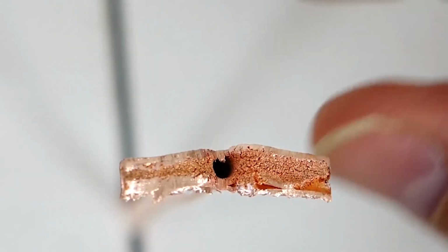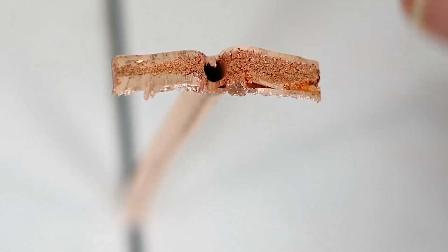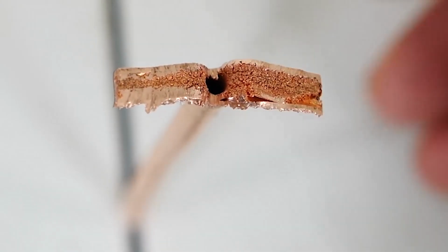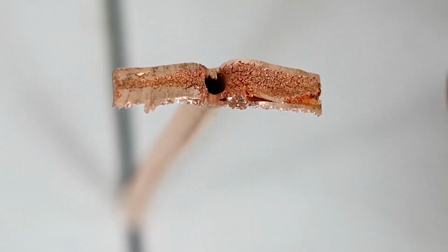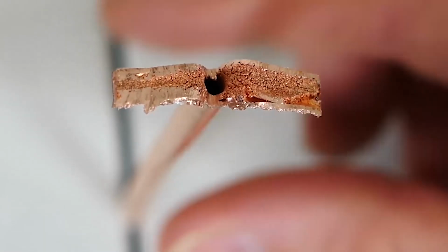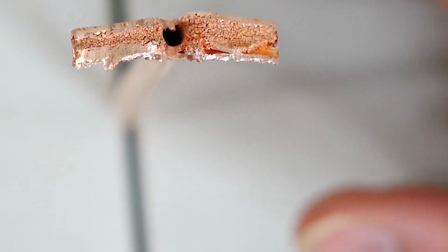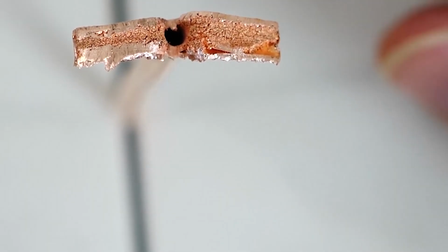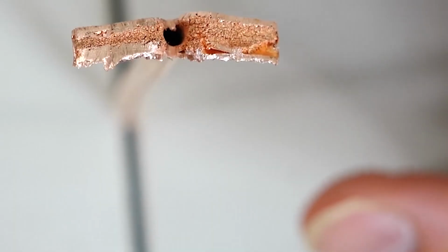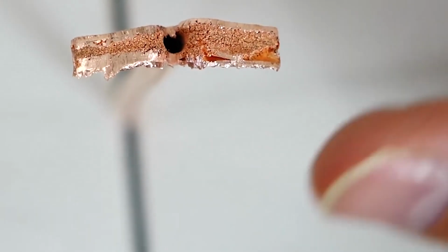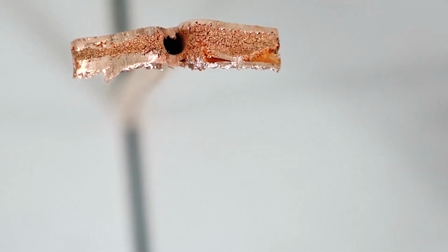And usually what they'll do is they'll get a regular copper pipe and they'll fill it with a little bit of water, and then they'll let that water boil, and then they'll seal off both ends of the pipe. So that all that's left in there once it's sealed off and cools down is a tiny little bit of pure water in a vacuum. And so there's a really low pressure in there because the water that was hot vapor condenses down once it cools down, but the ends are sealed, and so basically you just get a drop in pressure and a tiny little bit of condensed water.